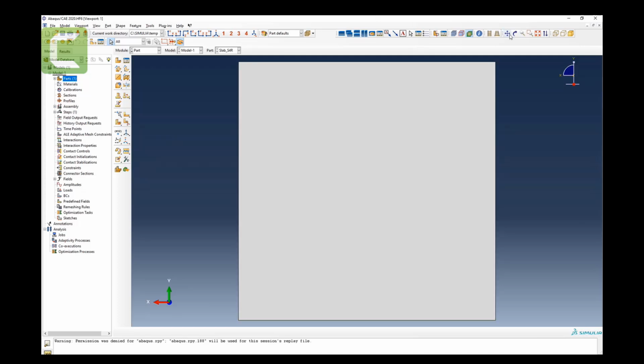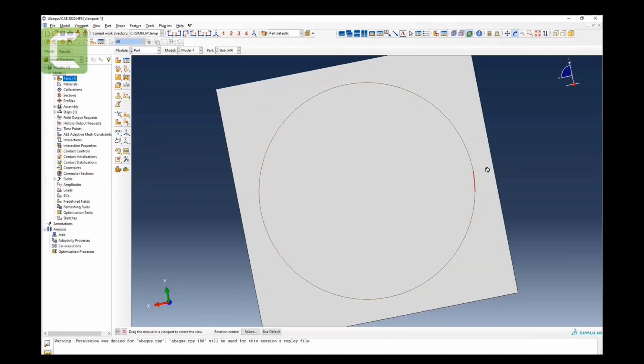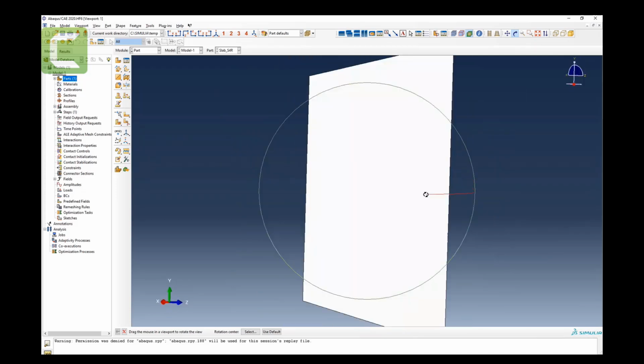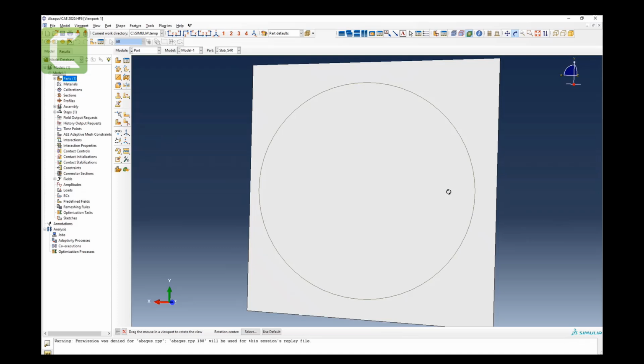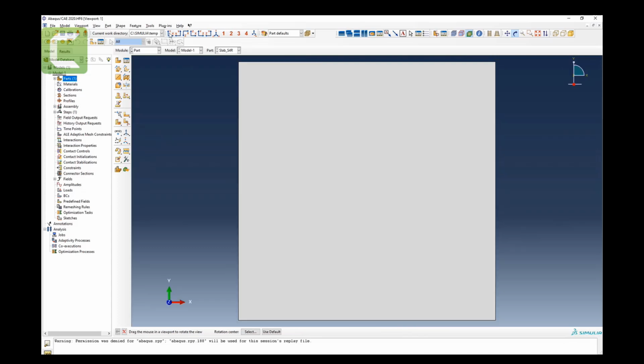You can rotate as well. If you have this button, rotate view, Control Alt MB1. If you do this, you can rotate it in any direction. So you can see that. Very simple. If you want to keep it in any of these orientations, you can come back here to the view menu and choose that view as well. Any questions? Any comments? So far, so good.